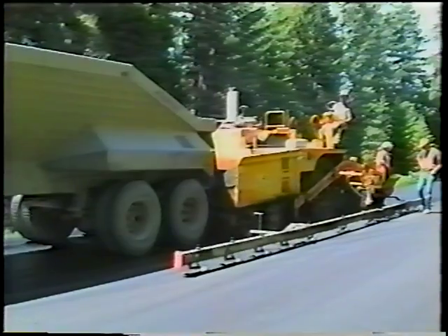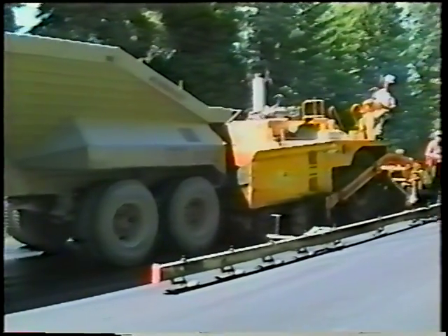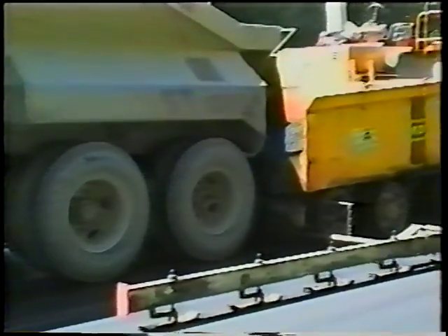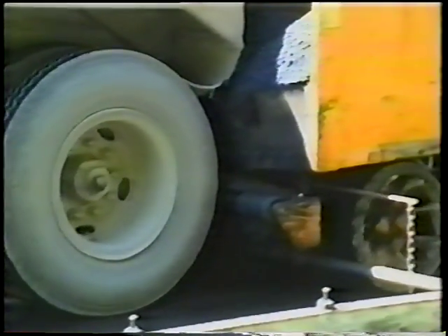As you can see, it's pretty basic. The wings on each side of the machine are used to channel the mix toward the paddles, which in turn load the hopper. A plate is mounted below the paddles to ensure that all the mix is picked up. Rear dump and conveyor trucks load the paver directly. Two push rollers mounted on the front of the hopper push the truck along as the truck loads the hopper.